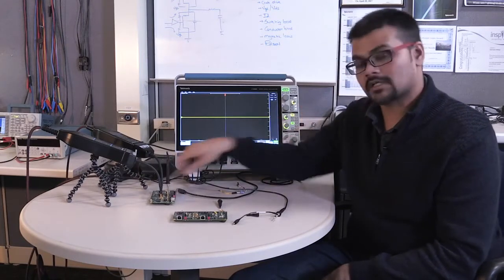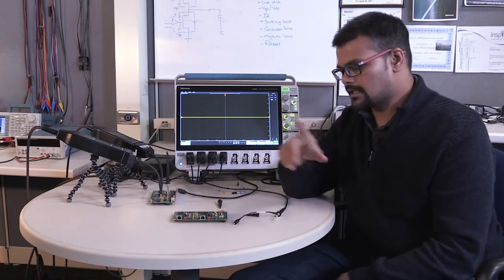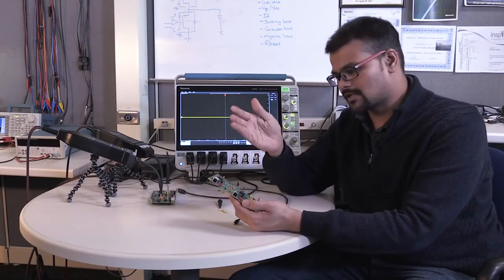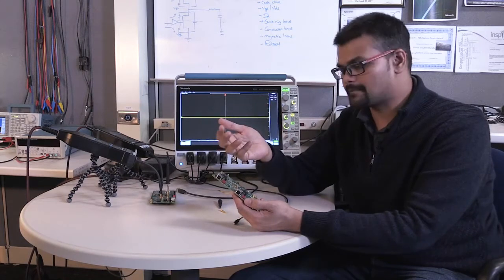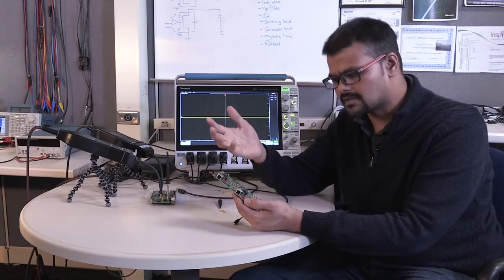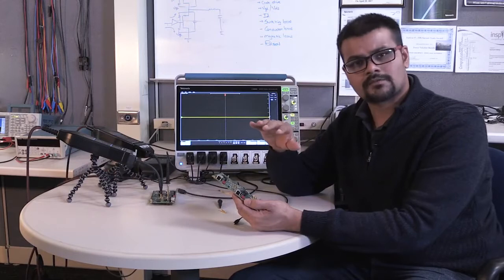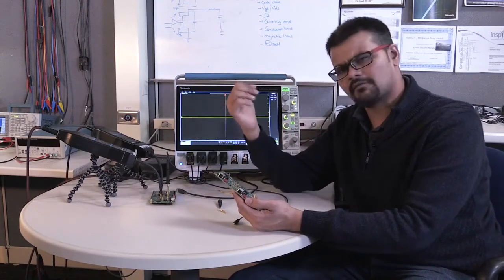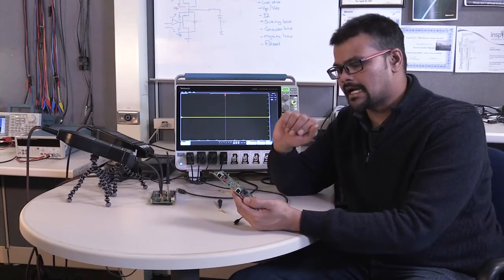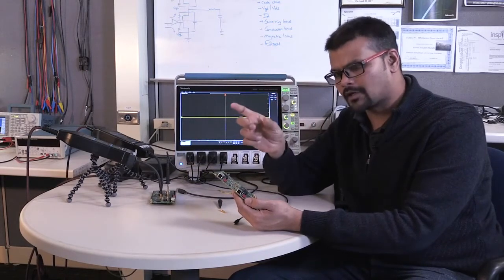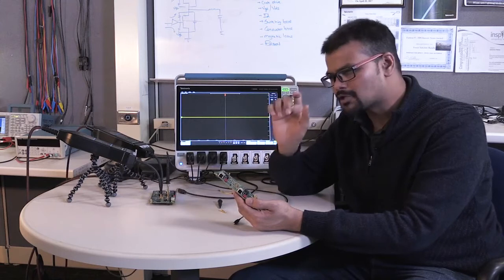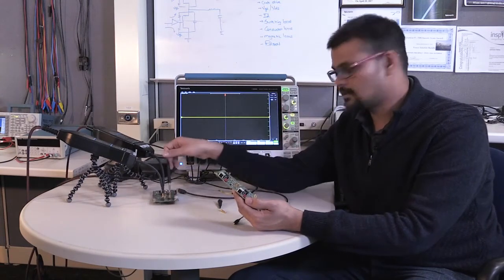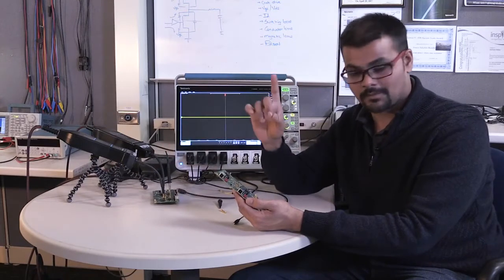So I picked one that is 1 gigahertz, and the reason is think about the switches we are trying to measure and the transition times, right? So most of the GaN products in the market right now, from GaN Systems, EPC, Transform, the turn-on times are usually in the 10 nanoseconds or 5 nanoseconds, 6 nanoseconds range, and we'll see a very similar example here, right? And if you think about how much bandwidth, with a very simple rule of thumb, you actually need to measure that transition, that is the number you come up with, right? So bandwidth is one piece of it.